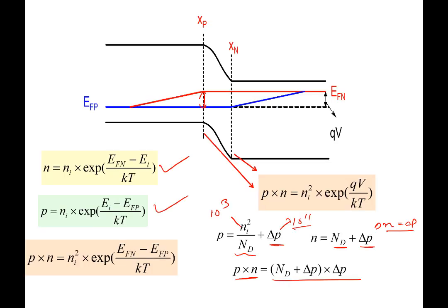So what is the assumption here? Well, you're looking at a case where you have applied significant voltage. Even if you apply 0.1 volt or 0.2 volt in a PN junction, you can do the calculation later on, and you will find that this is much larger than ni squared over Nd. So this is fine. There is no issue of saying p equal to delta p. It's there right from maybe 50 millivolts or 100 millivolts onwards.